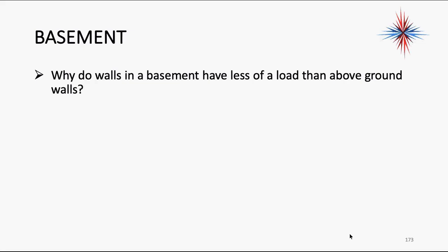So the combination of concrete block or concrete or brick or stone or whatever you have, plus the fact that the ground doesn't change temperatures that much, means basements have less of a load than above ground walls. Do we have to worry about the heat load of a basement? Oh yeah, if you're going to heat and cool your basement. Cooling becomes really easy, but heating sometimes becomes a problem.